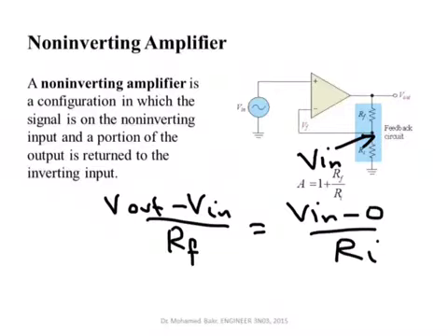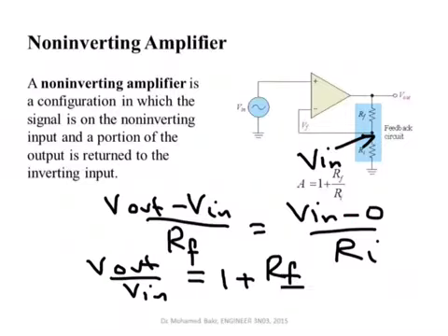If you sum all the terms related to Vn on one side, you should be able to show that Vout over Vn, where you get two terms from the input, 1 over Rf and 1 over Ri, summed to one another, and then you multiply both sides by Rf, gives that Vout over Vn is equal to 1 plus Rf over Ri.